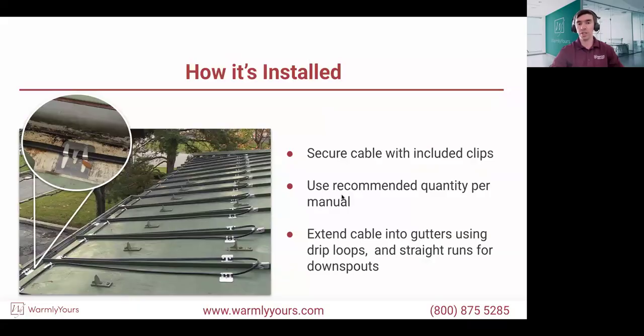And that's what you're actually going to see on our next slide that covers and shows you the metal roof section. Yes, here we are. Okay, so this is going to show you a pretty good example of the de-icing cable. This is the self-regulating. This is not the constant wattage. This is secured with the clips that we include for your system. These are the aluminum prong clips. Those are adhered with a really heavy-duty double-sided bonding tape pad, we call it. You make sure the surface is clean to adhere the pad and put the clip on.